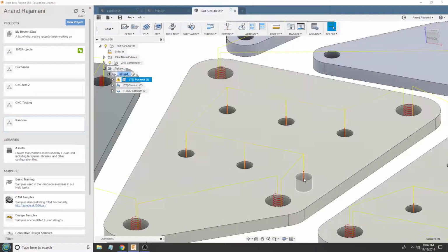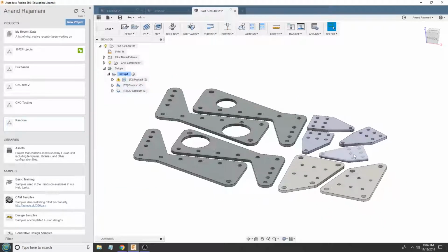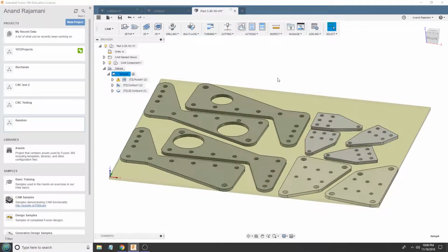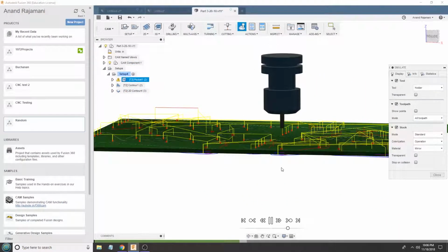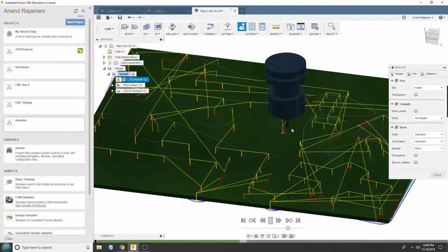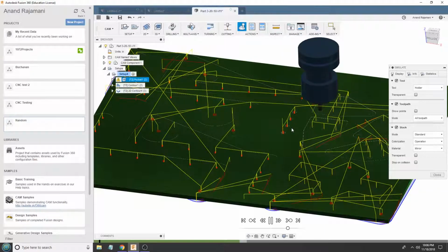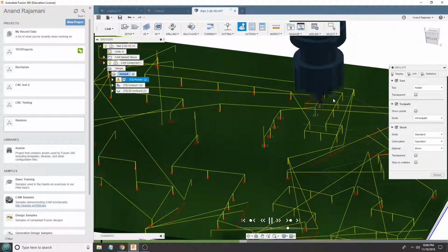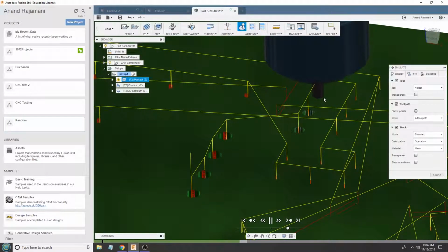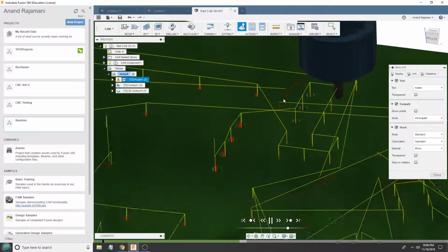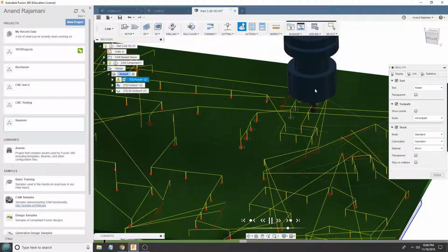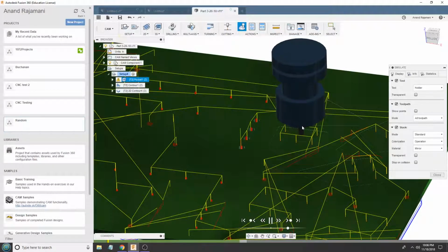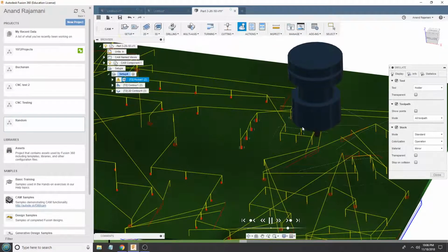You can see that. But that's good, because that tight spiral has been taking at 40 inches a minute, which means that my effective feed rate there, in terms of going straight down, is very slow. You see that? It's a very slow kind of plunge, a very slow kind of bore that it's doing. Maybe only like 1/100 of an inch, again right there. It's basically just vibrating as it goes down. So even though it looks like it takes a while, it's not taking that long, and also it's doing a very good job on those holes, making sure that it doesn't overload the end mill by taking too deep of a ramp or just plunging either.